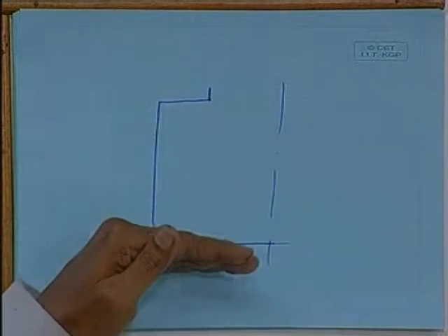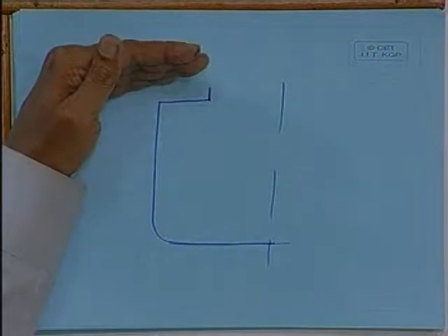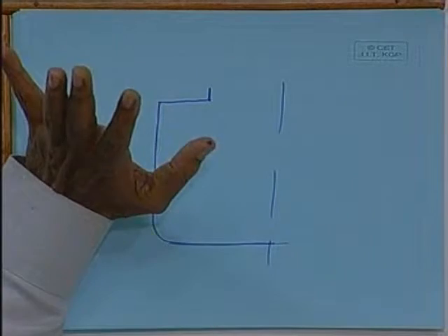Just assume that the top plating and the bottom plating farthest from the neutral axis have reduced in thickness by 25%. What is the increase in stress level? What will happen if these thicknesses reduce? If you have done an I by Y calculation, a section modulus calculation, then you will know that the section modulus contribution of this and this is the highest, isn't it?